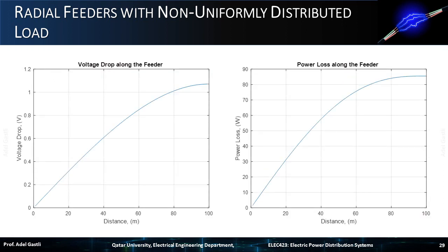After writing the full MATLAB script, we run it in the MATLAB command window, which generates the two plots that are shown here. Notice how the accumulated voltage drop as well as the copper loss, vary sharply and almost linearly, for distances below 50 meters, but very less and saturate, for distances above 50 meters.